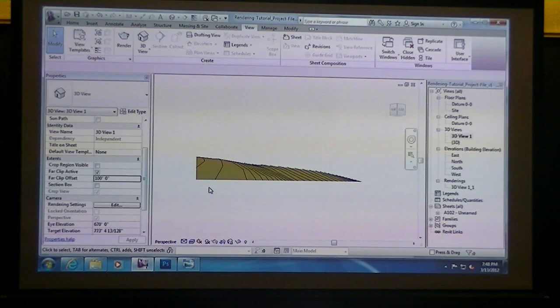You're essentially going to be setting all those components up to have materials, sending it back into the project environment and overwriting it. You'll get that dialog box that says overwrite, and you say yes, and then you're able to set up all your materials. If we have something that can just be white, can we leave it as a default? Yeah, you could just leave it as white.